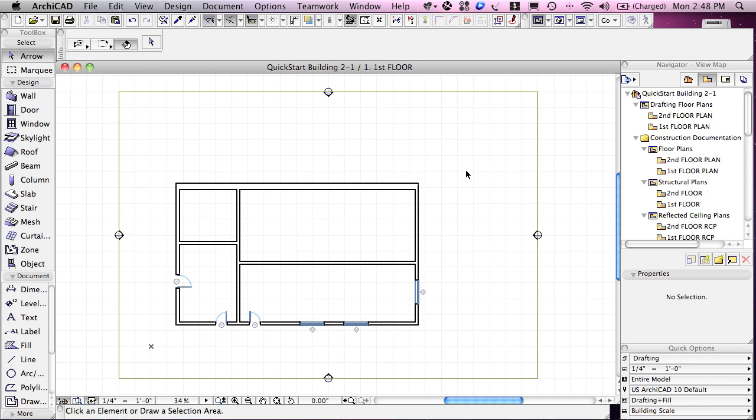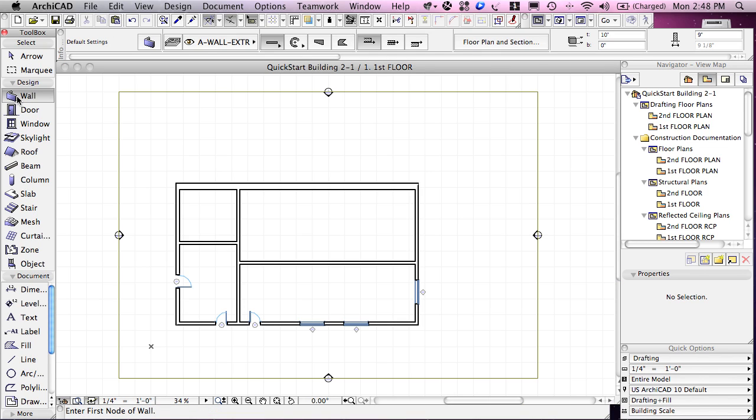Now let's proceed with this lesson. I'll activate the wall tool and let's look at how we input walls to a specific length. So I'll click to start drawing a wall, and you notice that as soon as I click it says distance 0, angle 0. The feedback that we're seeing on screen is called the tracker, and as I move around you'll see the tracker update to show me approximately where I am at any given moment as I draw.